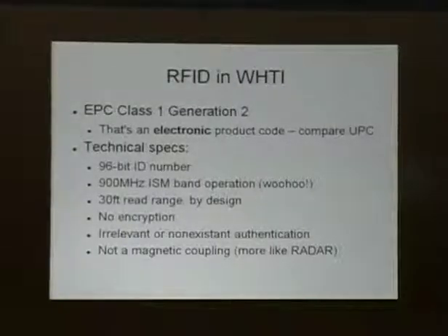This is doing that electronically. It's electronically changing its coefficient of reflectivity to alter how much radiation gets reflected back to the reader. It's a true radio broadcast. It's not an inductive coupling, which is why we can start applying radio techniques to it, because we're not limited to just an H field.